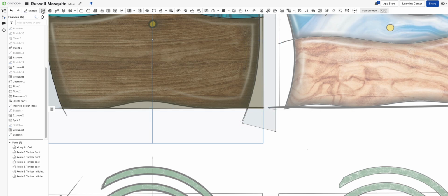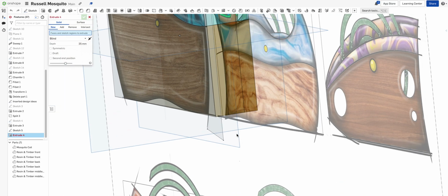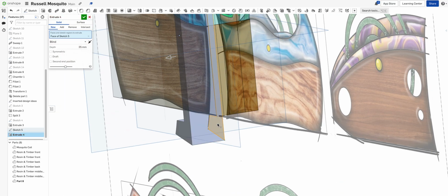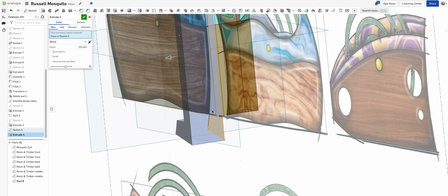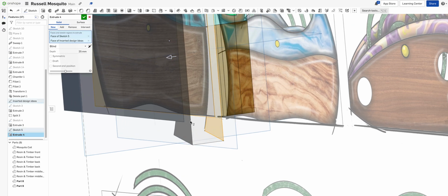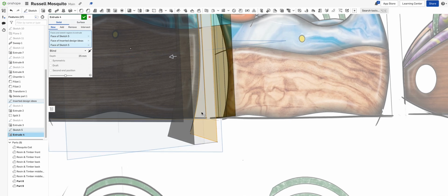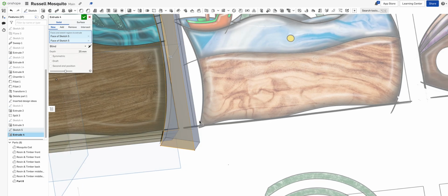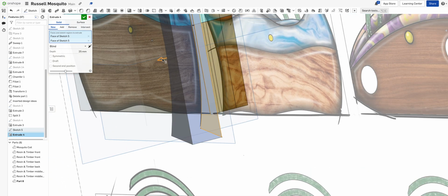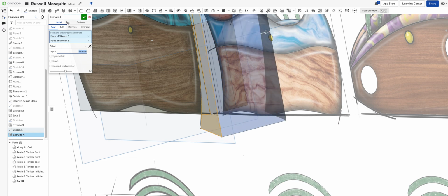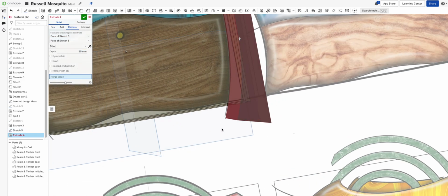I'm going to accept. I'm going to extrude. I'm going to spin my work into 3D to extrude. I want to extrude all of that shape. Let's just try and get that again. There we go. And you can see the same thing happen again. So it must be how I picked this shape. And by just double clicking it a couple of times, I've now got the right one. Then I'm going to drag through my work all the way through. I'm going to choose remove the material.